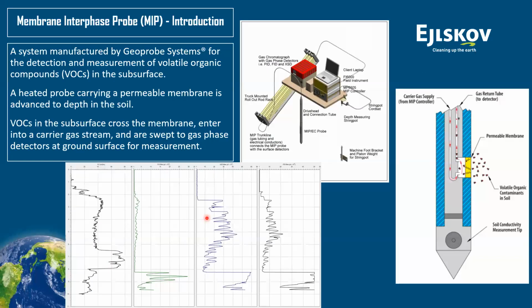How do we generate the data? As discussed, we try to use qualitative data. Most of you following this webinar are probably familiar with the MIP, the Membrane Interface Probe tool. It's just a heated probe that is hammered into the ground. At each interval, the user decides if you want to advance it 30 centimeters at a time, 40 centimeters at a time, or 50 centimeters at a time.